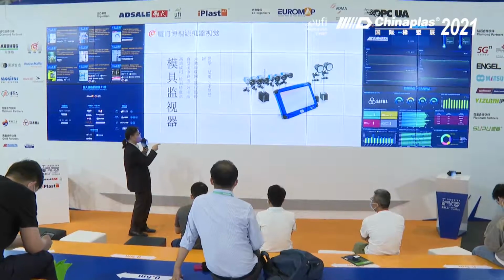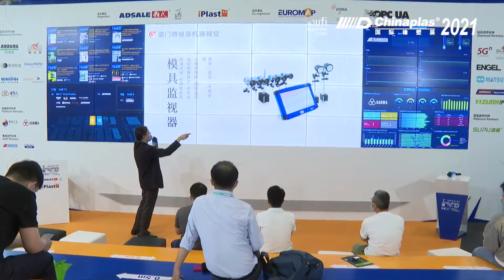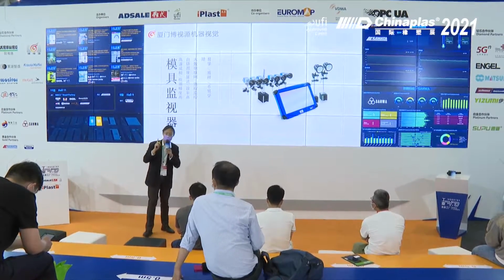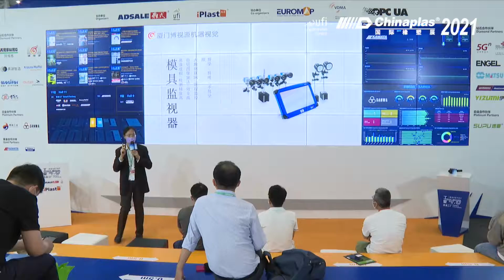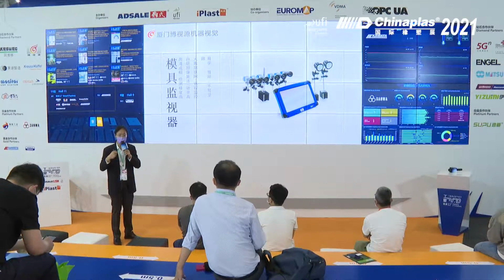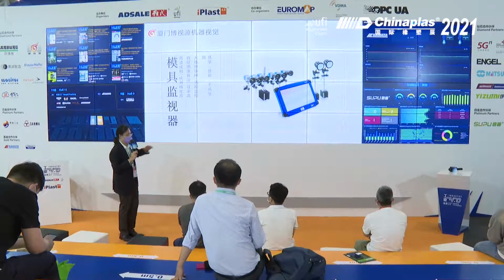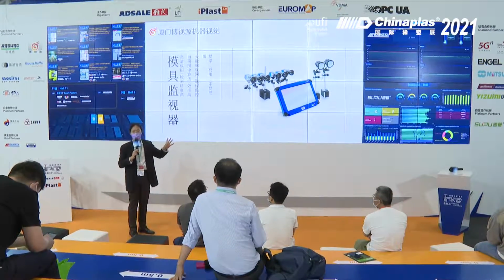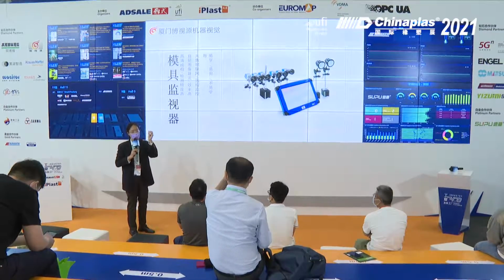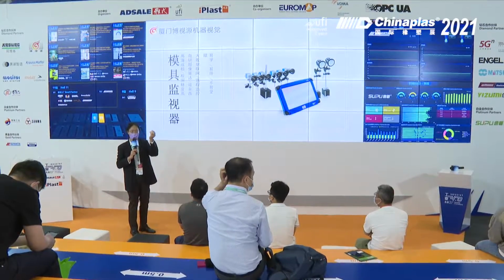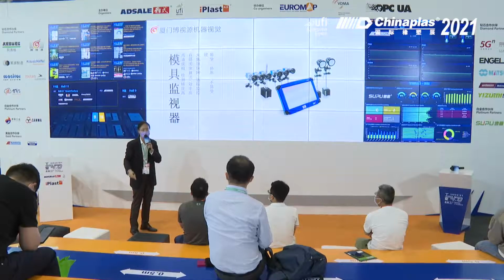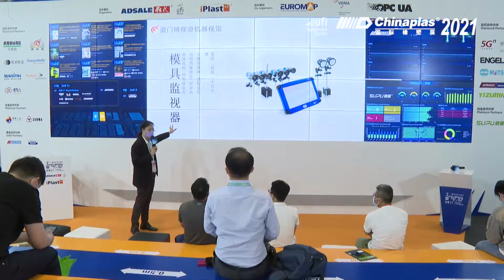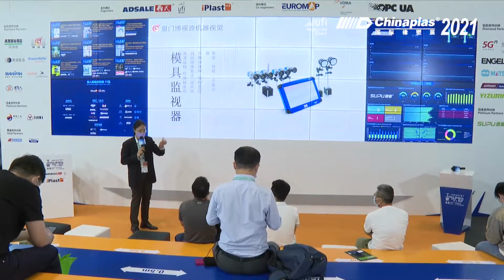And this is their mold monitoring system, and we have also one over there. So you can have 8 cameras together. And the key thing is, we use the mold monitoring to make sure the process is okay. Which means, if this is like a gate, and the mold monitoring system says, no, you have something left inside, or something didn't come out, it will stop the production. So the whole production is waiting for the signal of the mold monitoring system to say it's okay or not.